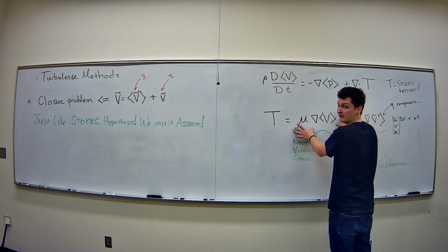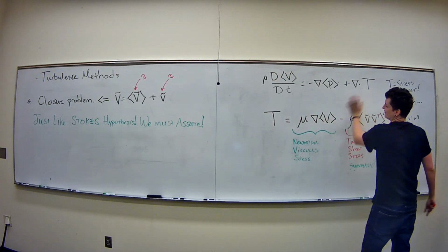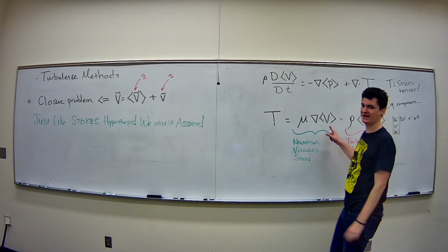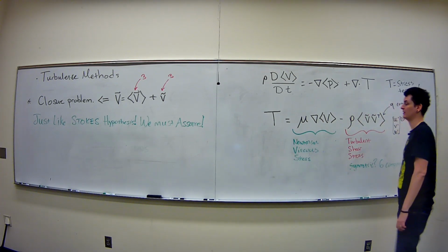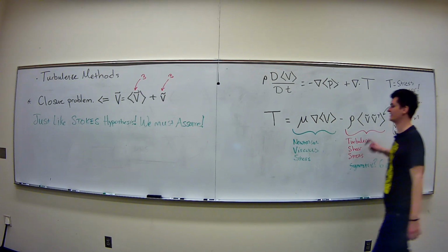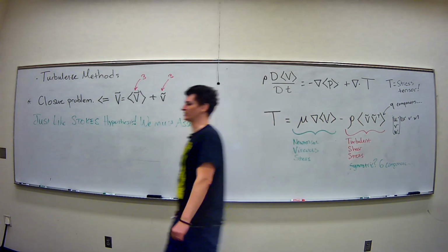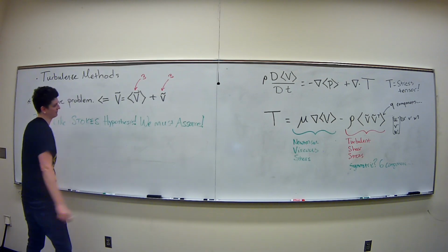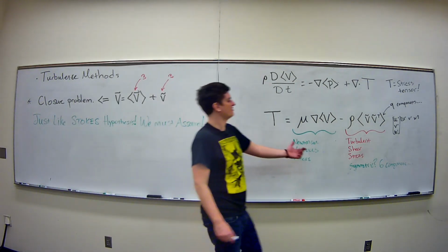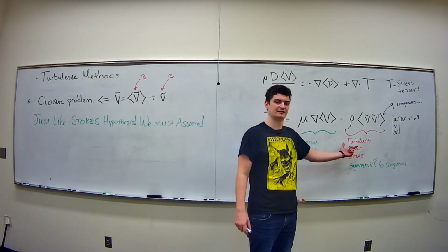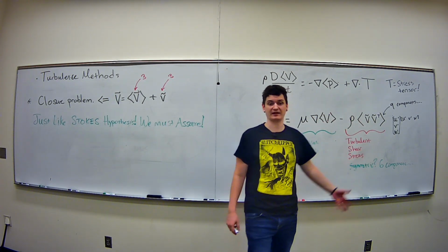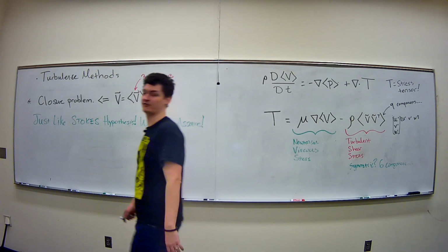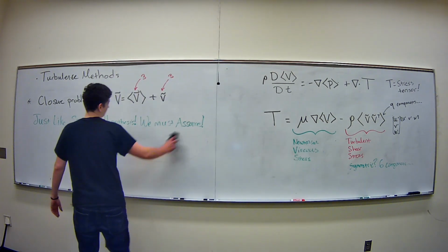This relationship, where I had a stress tensor, but I'm saying I can relate that to the strain tensor by this Newtonian viscous force. So what is one? I need one for this now, too. I need one for turbulence. I need a similar sort of Newtonian assumption of how that turbulent stress relates to the strain rate happening in the flow, of the mean flow. And that's what people did, right?